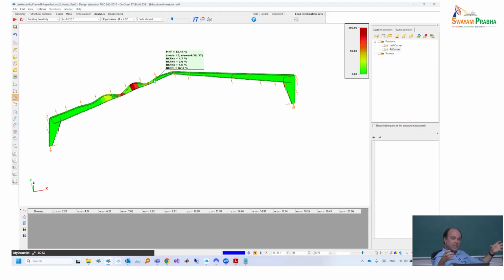They are continuous deformations around the structure. They fulfill all the compatibility requirements, as we saw on the first day when we thought about continuity by adjacent members. The rotation of the connected elements makes sense, so they rotate together based on the stiffness and the elastic stress level. So they are realistic deformations, so why not calculate deformation energy from them? It's simply a stiffness matrix multiplication. We already have the stiffness matrix for a section. We multiply the stiffness matrix with the deformation, and we calculate deformation energy.